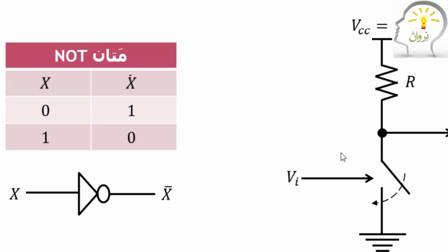So now you put this value into the voltage divider formula. R2 is infinite, which means maximum, so the voltage also becomes the maximum, so 5 volts. So the answer is 5 volts.